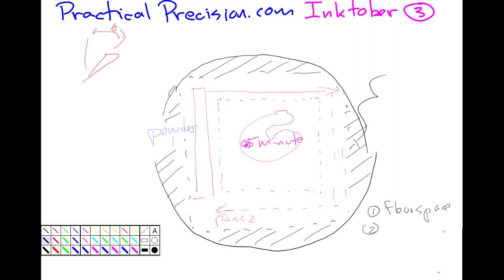And another one is time, actually, because we've already established that this is a pressure vessel of some kind. So we have to pump it down to vacuum at one point, and then we're going to backfill it to some partial pressure with argon or something like that. The larger that volume is, the longer it's going to take to pump down. So that's another throughput consideration. Those are just some general considerations.